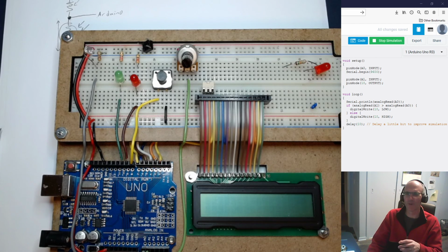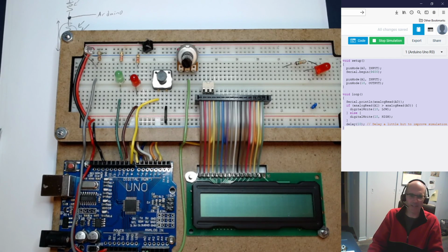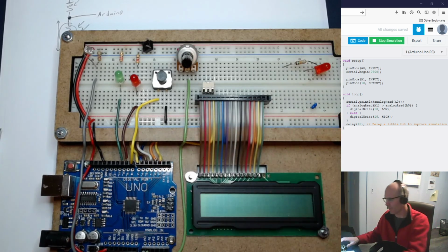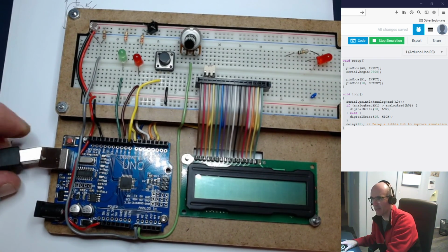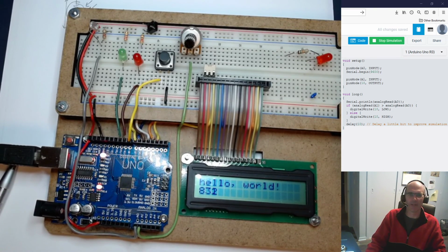When you've got code that's working in TinkerCAD, copy that code right into your Arduino IDE. You can copy and paste right into the Arduino IDE, and then remember, before you go to upload your code, to make sure that you're on the correct serial port. Right now I'm not showing any COM ports because I'm not plugged in to the board. When I plug in like that, it figures out that I'm hooked up on COM3. Sometimes you'll have other ones working.